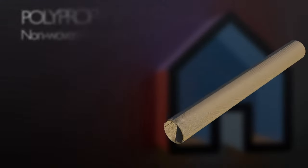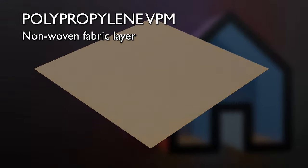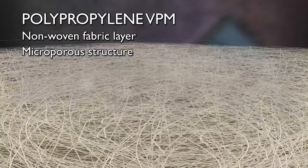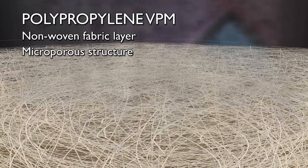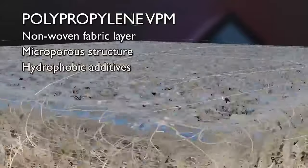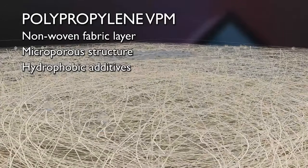To achieve this combination of properties, vapor permeable membranes are typically manufactured from polypropylene, the fibres of which are laid down to give a structure like a bowl of spaghetti. This has many microscopic pathways, which will restrict the passage of denser liquid water but allow the passage of vapour. In addition to this, the material incorporates hydrophobic additives, which actively repel liquid water, trapping it at the surface.